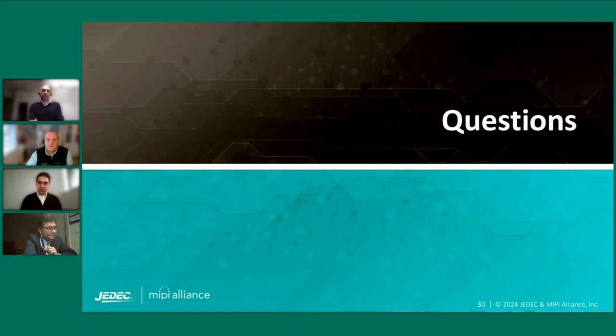Okay, thank you. When the high-speed reset mode was discussed in M-PHY work group, we had to choose one default high-speed rate to be used. And this is because whenever UniPro issues a reset, the PHY will fall back to the default rate and gear. And because in this particular application, there was no other way envisioned to have selected a different rate, it was decided that after a reset, the PHY would default to high-speed gear 1 rate A.